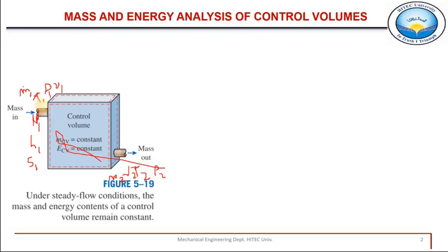We can say that the values of all these thermodynamic properties change with respect to position, but with respect to time all remain constant. Then it is a steady flow process, meaning all these intensive or extensive properties do not change with respect to time. It also means that when we talk about the enthalpy change, kinetic energy change or potential energy change from inlet to outlet, this change is not changing with respect to time.